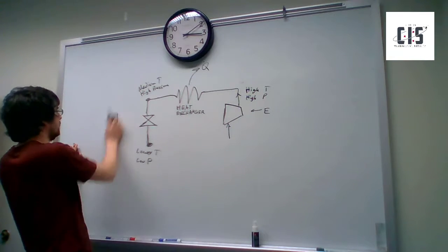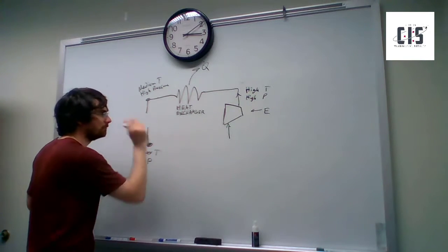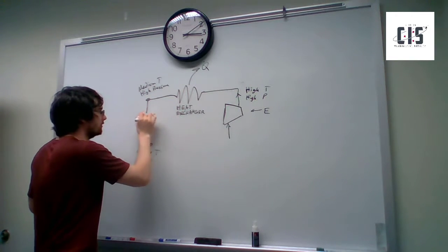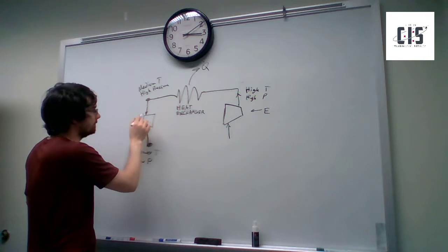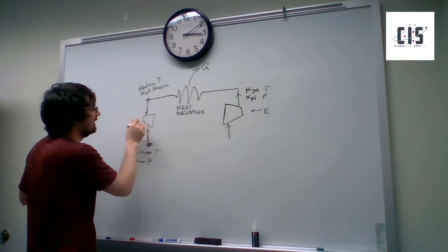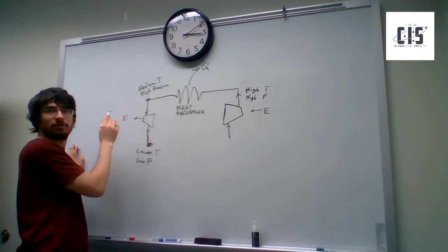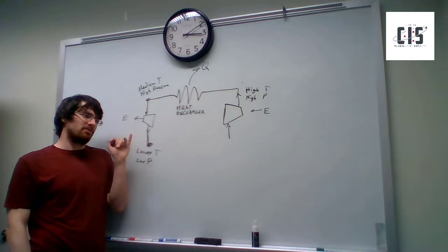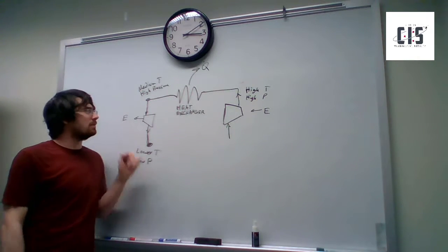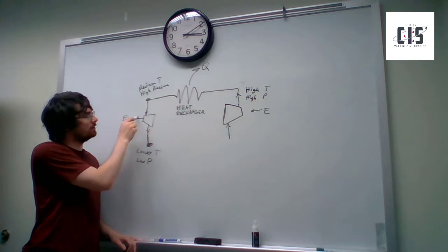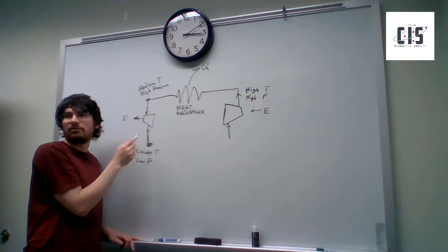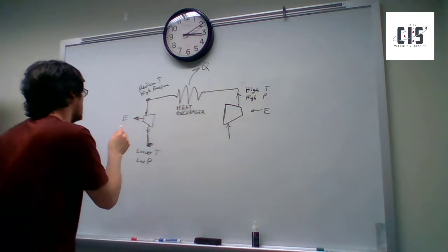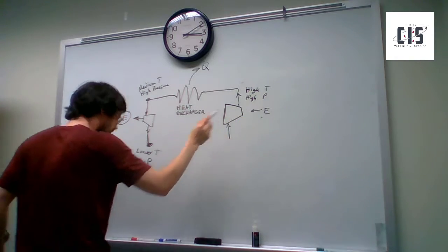So let's also add a turbine. Let's try that. So we have, let's see, this direction. So the gas expands going through it, and it also creates work. Oh. That's the important thing, because it's doing the same thing as the throttle, but it's also putting out work. So there's a temperature drop from the pressure drop, and a temperature drop from some of the work that got done. Now, this amount of energy is nowhere near that amount of energy.